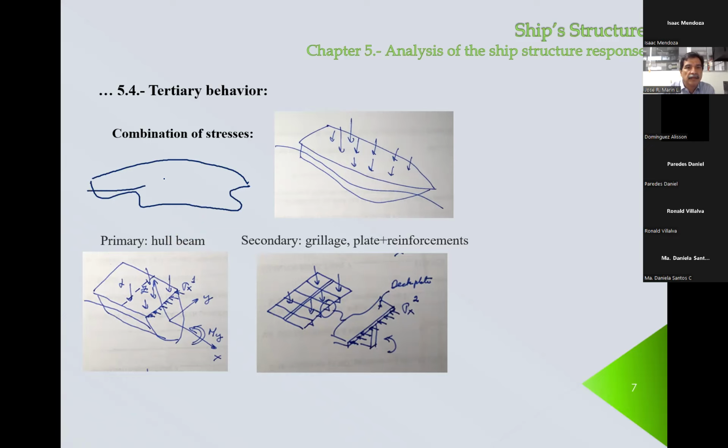So we're going to have a crest here. So we have extra buoyancy in this area. And in this case, on the deck, we're going to have tension. Okay, so what I'm saying is that primary stress could be positive or negative. Okay, now let me erase this because I don't want to get any more.